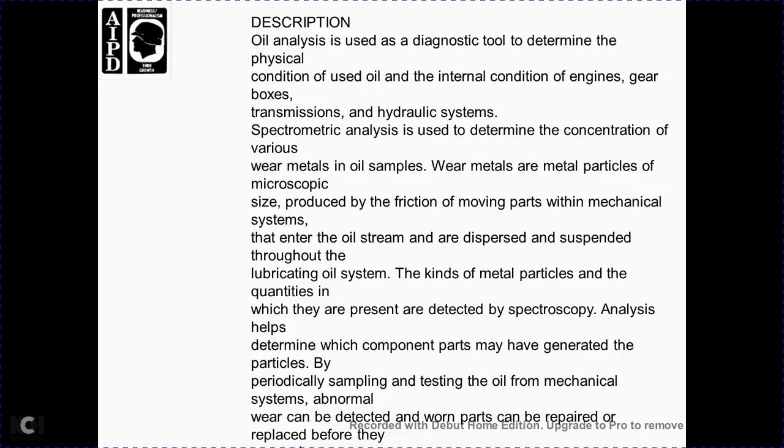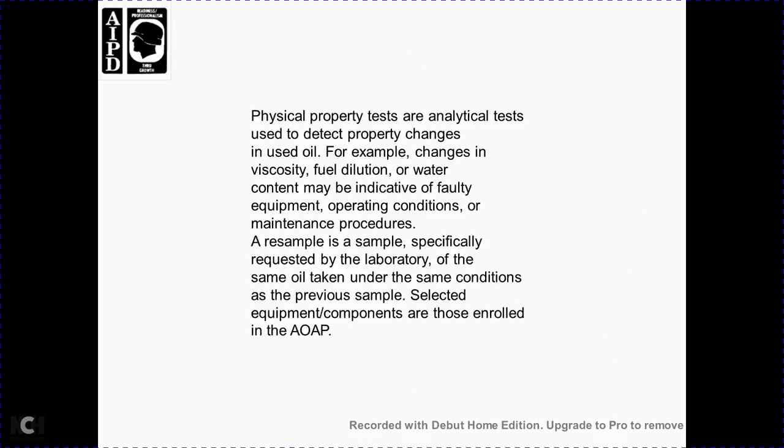Through the testing of the oil, when mechanical systems are abnormal, the wear can be detected. The worn parts can be repaired or replaced before failure. Physical property tests and analytical tests detect changes in the properties of the oil.